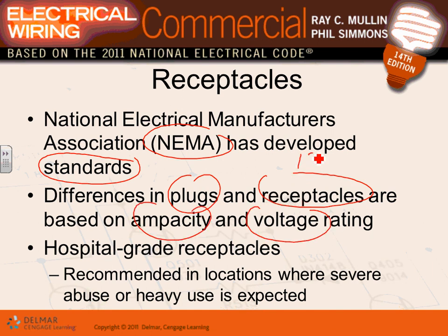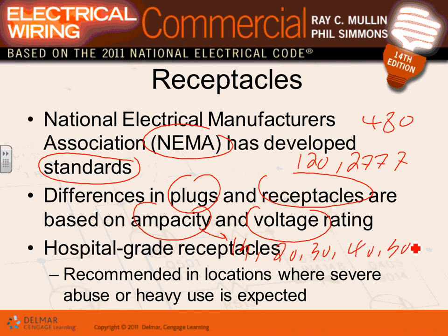So if I have a receptacle rated for 120 or 277 or 480, you're going to have receptacle ampacities from 15 to 20 to 30 to 40 to 50 and so forth. So you would hope they will be configured differently, so when you plug your equipment into these receptacles, you're not going to burn them. Very, very important, guys. I know, Adam, you guys wired a hospital grade receptacle with Mr. Lee. Hospital grade receptacles, guys, are a major part of what we do. Locations were severe.